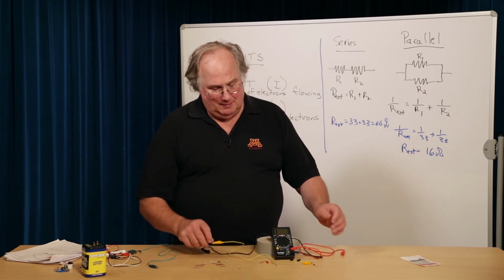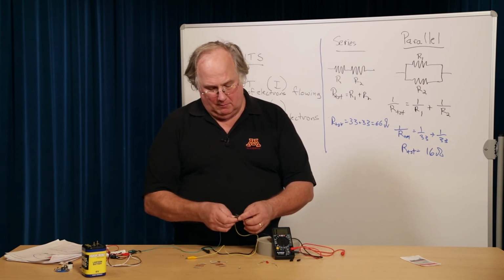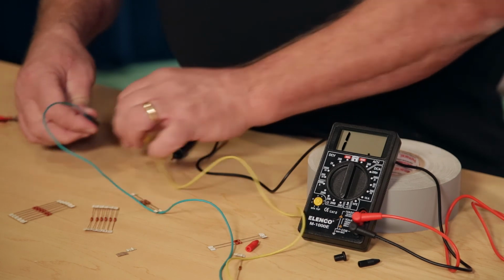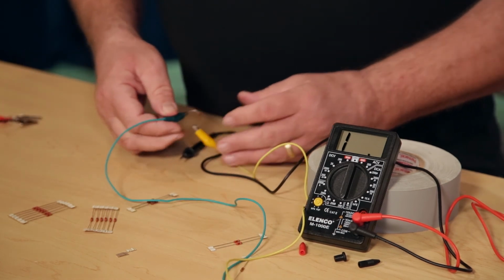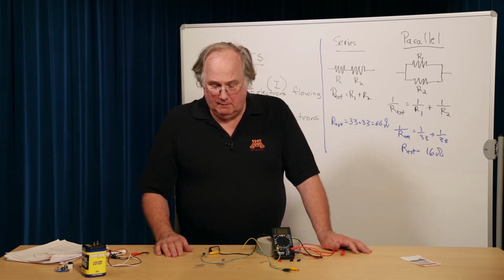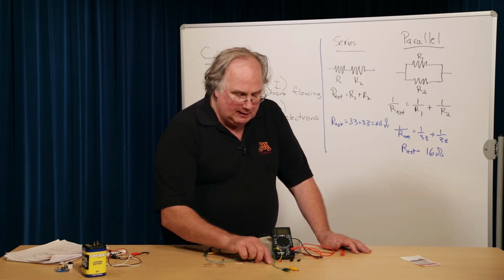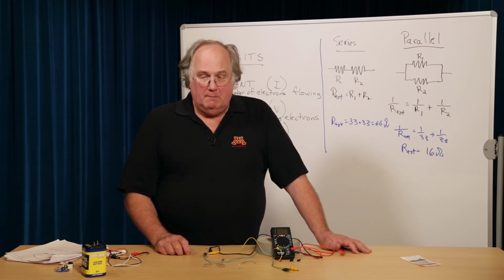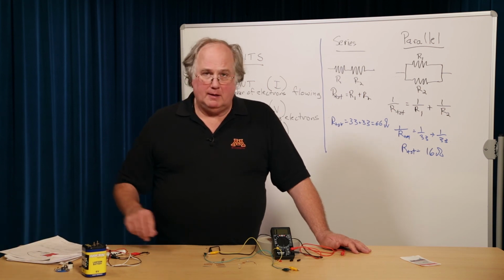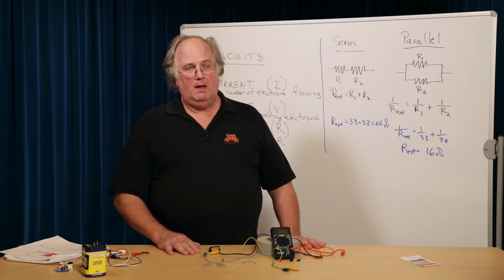Okay, the other thing I want you to do is to take 10 ohms and put it in parallel with 33. So we'll hook up a parallel circuit, and you can predict and measure the resistance of the parallel circuit. You should have several different varieties of resistors in your package with which you can make different circuits. Our next lab, I think we do some complicated circuit networks, and we'll come back and talk about that. So, okay, there we go.